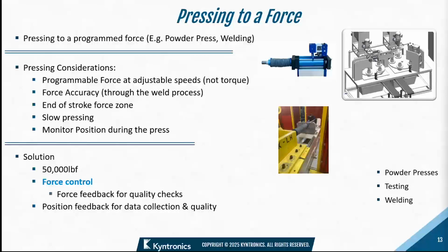So in this example, this is actually a weld. So during the weld, you want to maintain a certain force. And as the weld is produced, obviously the force is going to change. So you want to maintain it, and it'll go in a little bit slowly. And so it's critical on some of those important welds and quality checks. So again, force mode.